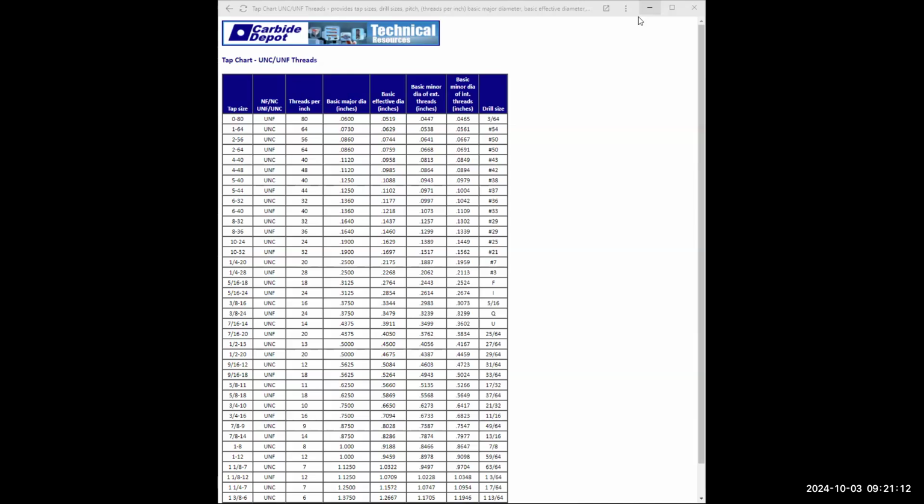Click. Hit F8. Turn on the ortho. Click, enter. And this is going to be 5/16-18 UNC-2B. Enter, enter again.